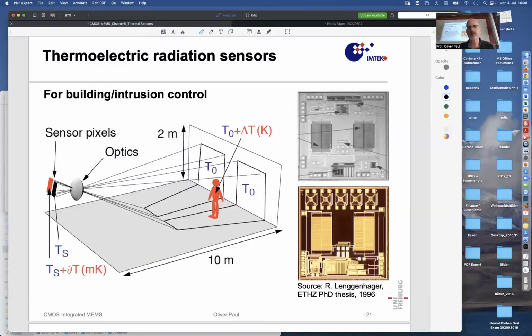So you may have something like a millimeter of membrane, 1,000 micrometers, 6 micrometers thin. That's very flat. It's like a sheet of paper. And this thin sheet of glass absorbs heat from outside and gets hotter in the center. It is supported on the edges. The chip is at temperature T0, but because the membrane heats up, in the center it will be hotter, and then heat will flow away towards the suspension, the chip, and the temperature increase under this absorbed heat is what we measure.